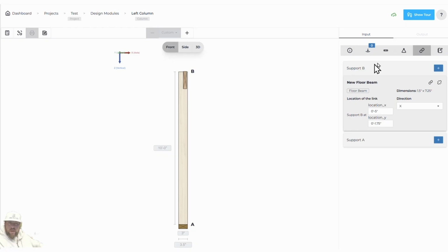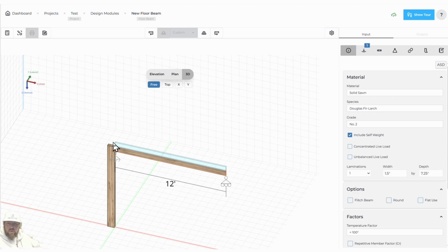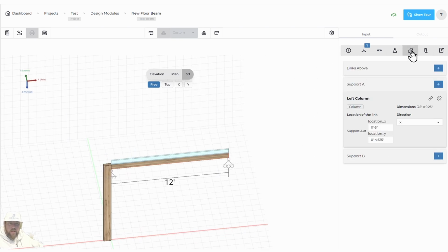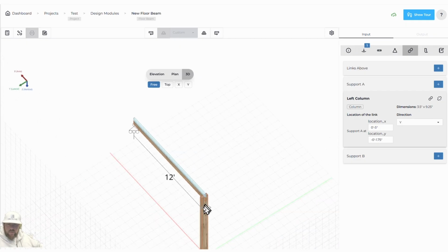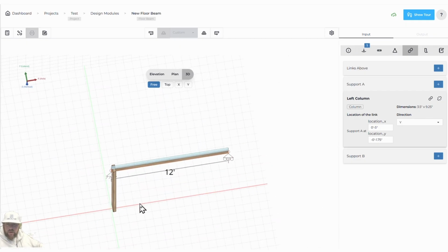When you do the calculations on this, it's not just taking a single on-center beam and putting it on an on-center column. It respects offsets. The column has offsets on it. It's also directional. So if you want this to be oriented in the other direction, you can flip it like that. And you can offset it and move it left, right, flush mount it however you want.